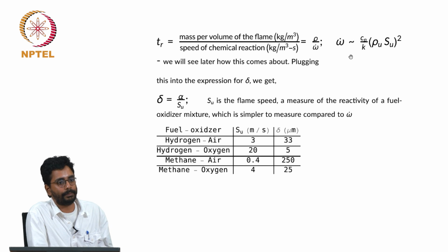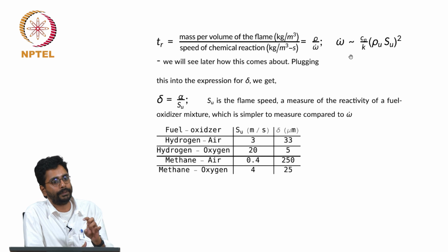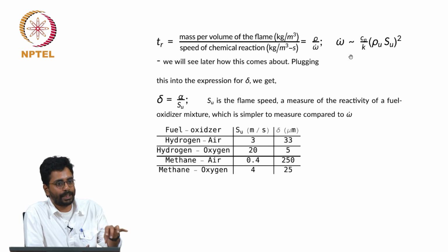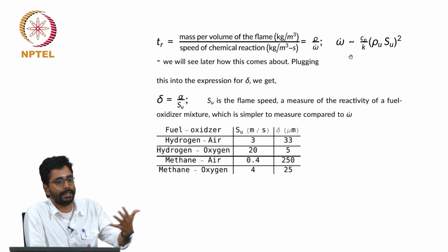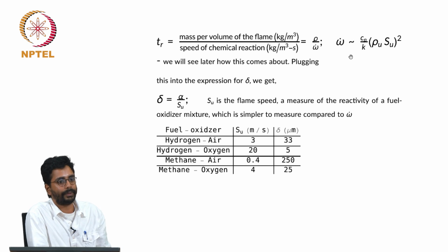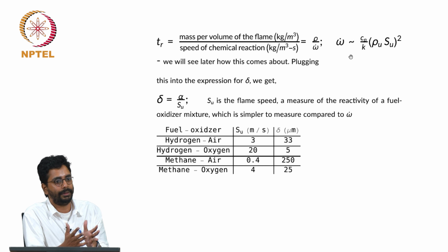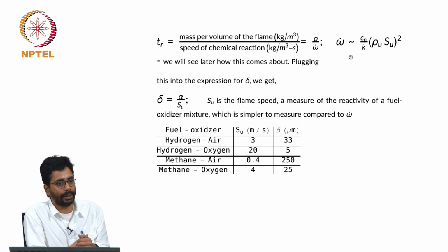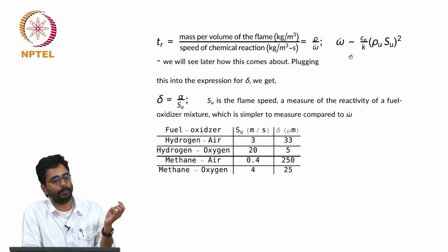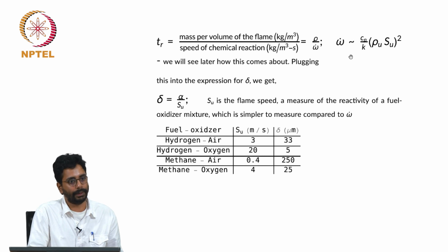It is called the S200 booster, which has a propellant consisting of ammonium perchlorate, HTPB, which is a rubbery material that acts as a hydrocarbon fuel, and aluminum. So, all these are mixed and made into a solid block which can then burn. Generally, the ammonium perchlorate is the oxidizer, and HTPB and aluminum are fuel.